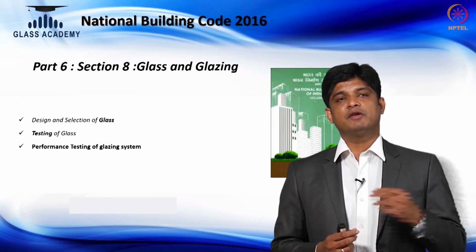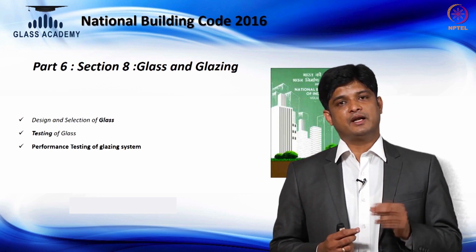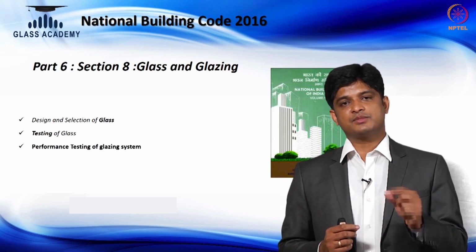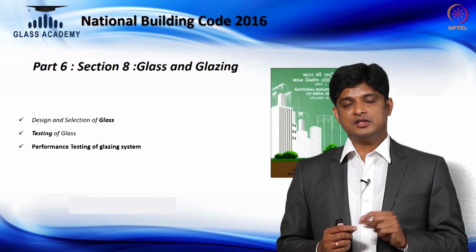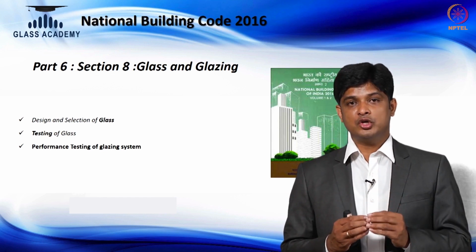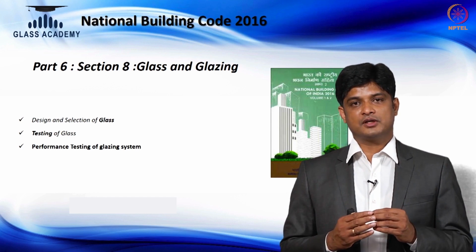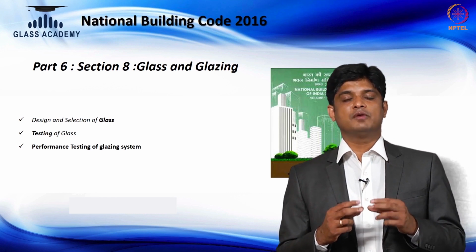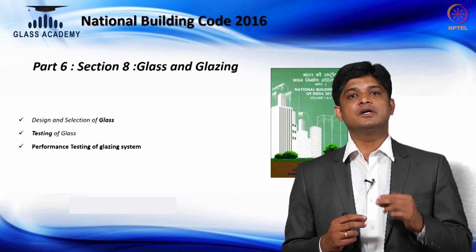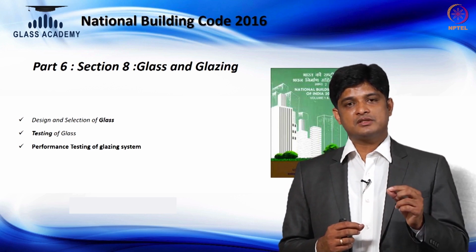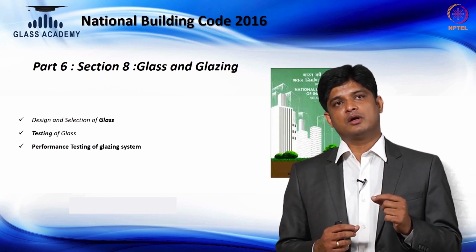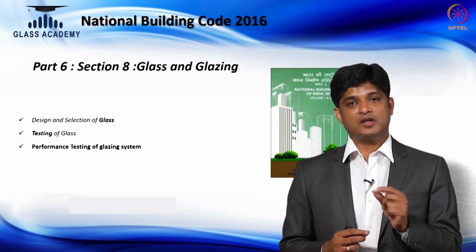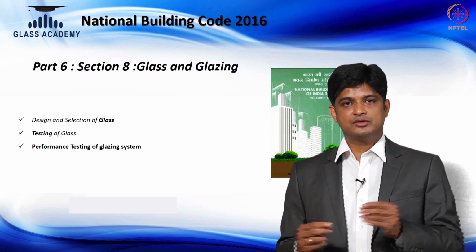So to recap what we have covered in this section: NBC 2016 has a new section called glass and glazing, which is section 8 under part 6, structural design. This section 8 is new and covers vast detail. What we have taken you through today is to give you an idea of what is covered in the overall NBC. Very precisely, this portion of the session will help you understand how to design or select glass for a building, and what the testing requirements are for glass and for systems, or the glazing division.